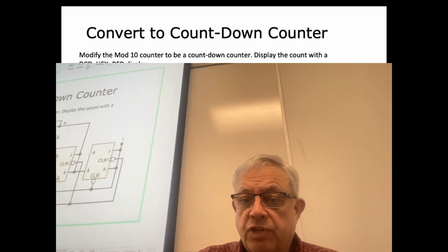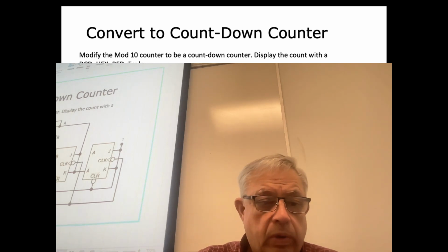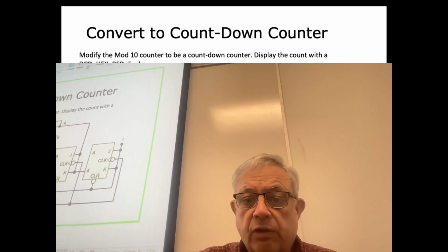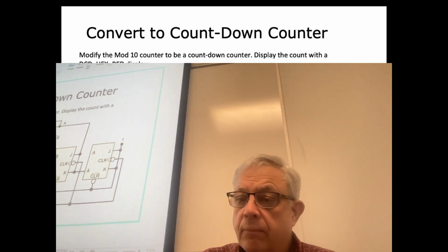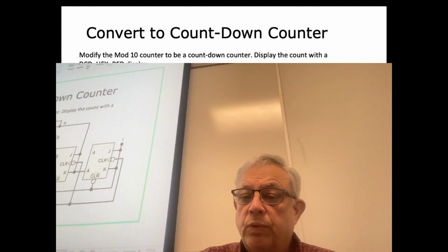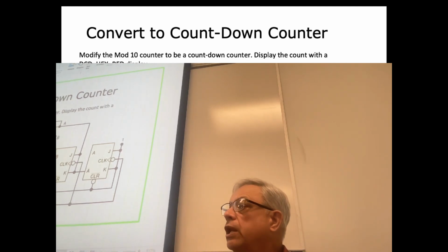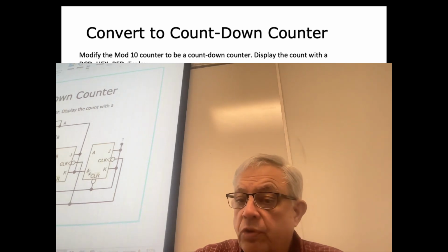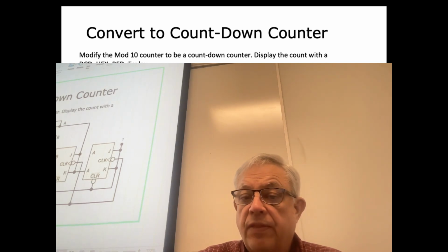The last thing you did was the up-down counter. Oh, I didn't bring the up-down counter in. I just showed the down counter. What did we change for the down counter? We took input from the Presets. No. What made the difference? All the logic is driven off of the Q naught line for the down counter. So we take A naught, B naught, C naught, and D naught, and they ran the down counter.